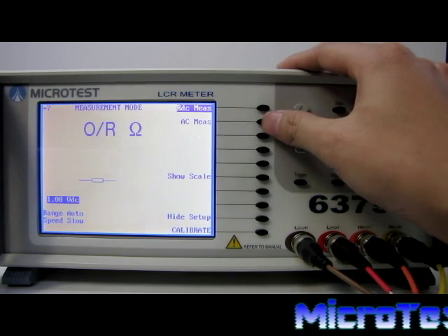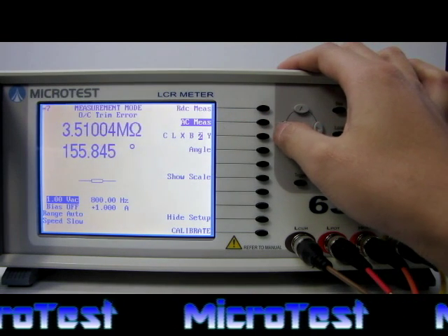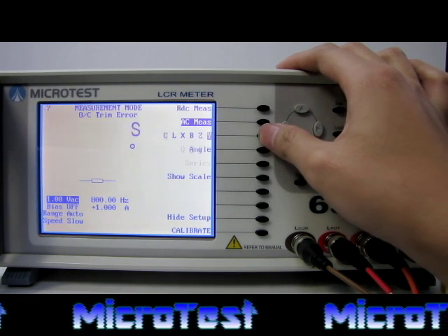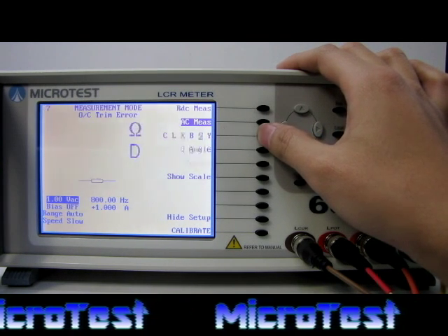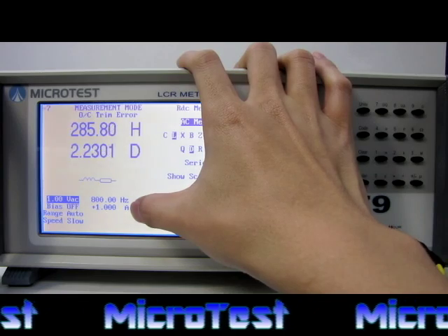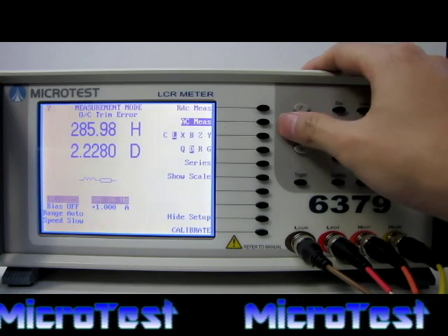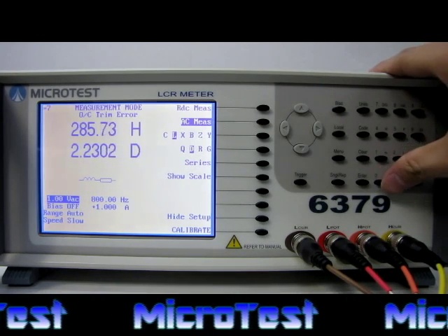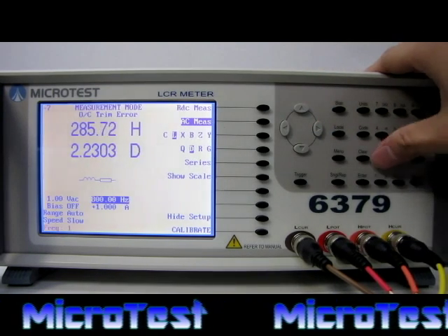Press S2 on the main testing screen and select AC measure. S3 and S4 show the different test values that can be obtained. Press repeatedly to change the values. After selection, the bottom left has voltage, current, and frequency that can be adjusted as needed. The current value will not be used unless combined with the DC bias. Press the arrows to select voltage and adjust values by using the number keys on the right. The same can be done for the frequency.